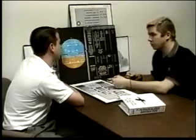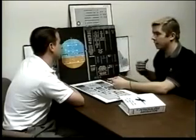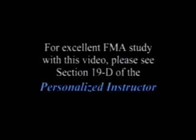So if the captain pushes forward 5 degrees and the co-pilot pulls back 10 degrees, it's going to come back 5 degrees total. What about the boxes that you see on the outside? That's just the maximum range for that side stick order indication. Again, here we can see an example of beta target in blue.